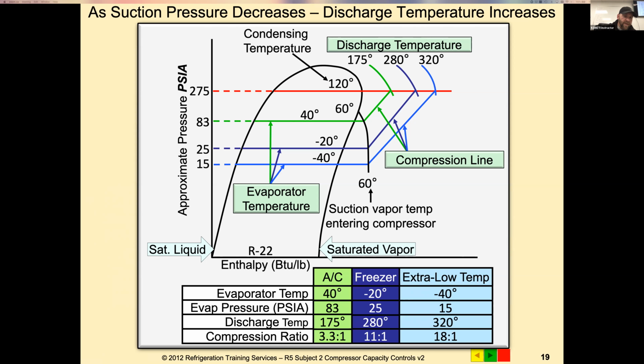But the importance of enthalpy is really understanding what this chart's telling us and where the actual heat pickup is taking place. The reason is that line stays pretty consistent in the curve, so we're picking up about the same amount of heat at the evaporator, right? But because we push out so far past that refrigeration curve, it pushes out that angled line through the heated compression. What's really going on inside that compressor is there's less vapor per stroke, and what vapor is there is trying to pick up as much heat as it can, and it's overheating. Does that make sense? Yes, sir.